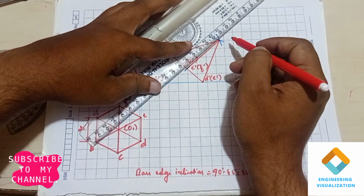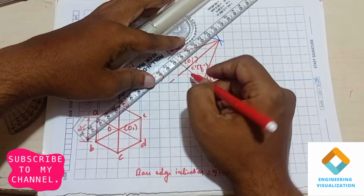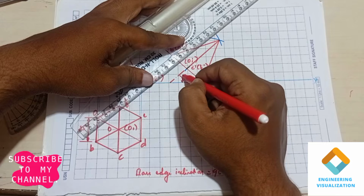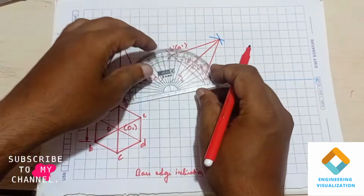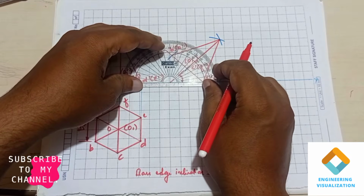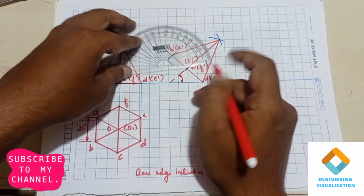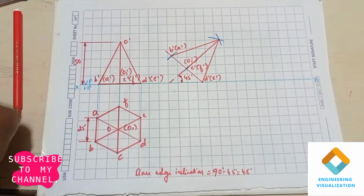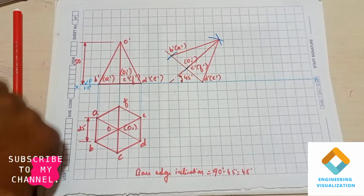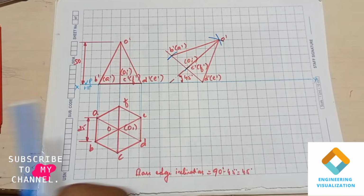So here I will be extending the axis in order to show the angle, because the angle of inclination to HP they have given with respect to the axis here. So you can cross check with the angle. So the angle you will get here is 45 degree. So now draw the projection lines downward here to draw the second position top view.